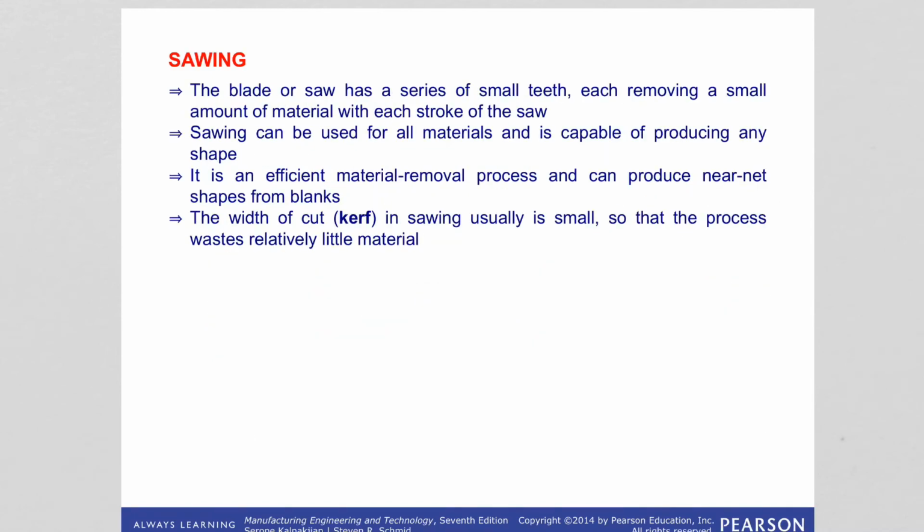So sawing is a common technique, and we have a blade or saw that has a series of small teeth, and each removes a small amount of material with each stroke of the saw, and the chips that are produced are contained within the spaces between the successive teeth until the teeth pass from the work.